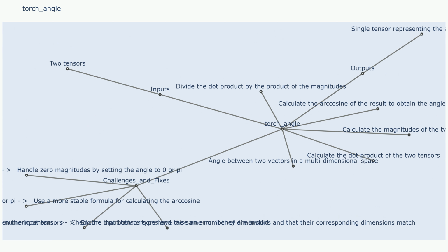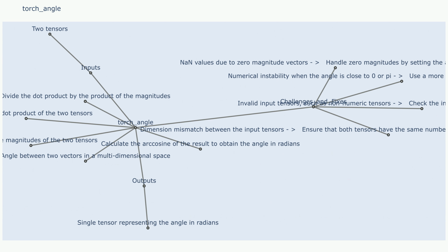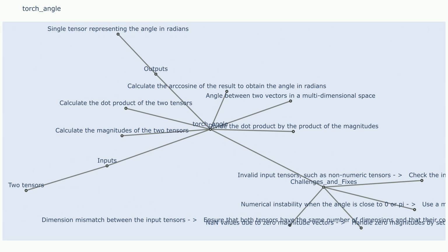Steps: setting the torch angle, the torch is adjusted to the desired angle relative to the workpiece. Starting the welding process, the welding process is initiated, and the torch is moved along the weld joint, maintaining a consistent angle throughout the welding process. The torch angle is carefully maintained to ensure a consistent weld bead and penetration depth. Inspecting the weld: once the weld is complete, it is inspected to ensure that the desired weld quality has been achieved.